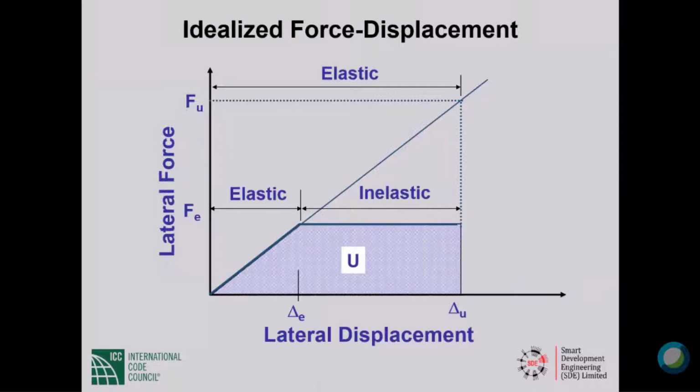As the earthquake-induced forces equal and then exceed F sub E, the structure will start cracking and yielding in places. That will be the end of elastic displacements and the beginning of inelastic displacements, which will not follow a flat top as in my idealized picture. But anyway, the point is that now there is damage associated with the displacements. The earthquake passes, we will not get our structure back intact. The damage will have to be repaired.